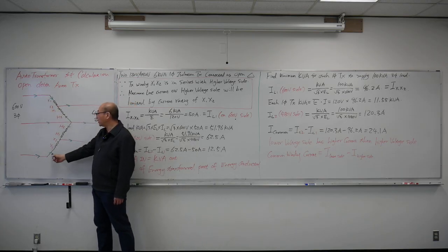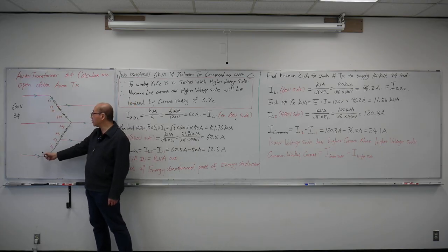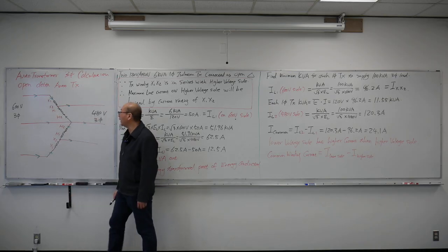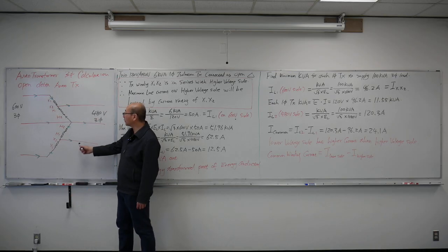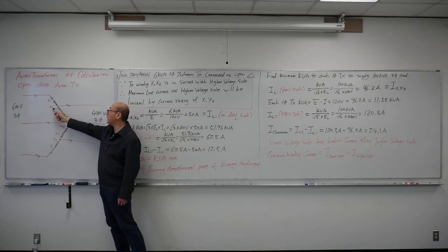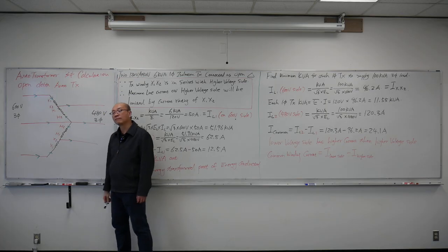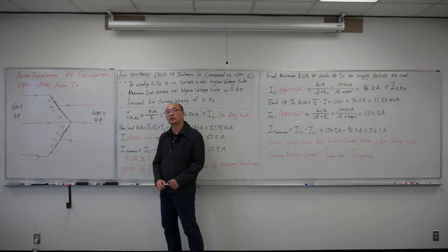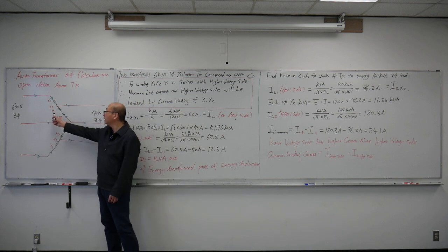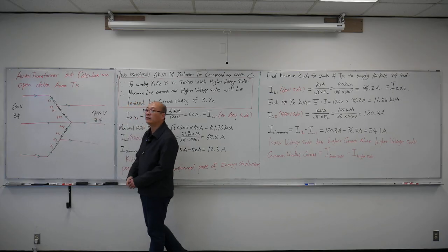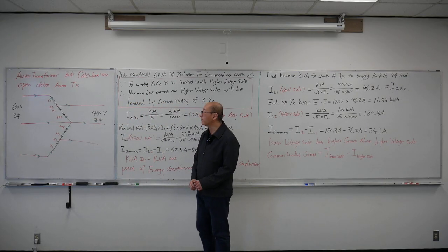The X1 terminal of each transformer is connected to the high voltage side, and the low voltage side is made by connecting each transformer's X2 and H1, because we connect those isolation transformers as auto transformers, so we have to connect the high side and the low side together. At that common point, I'm going to bring out one wire for my low voltage side.